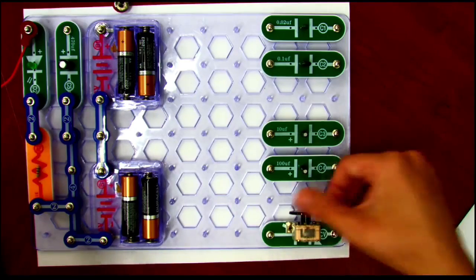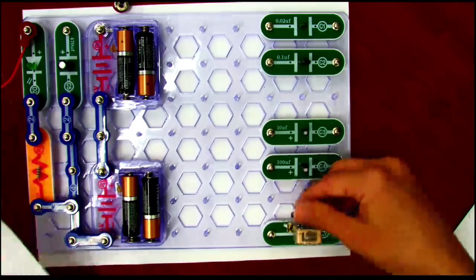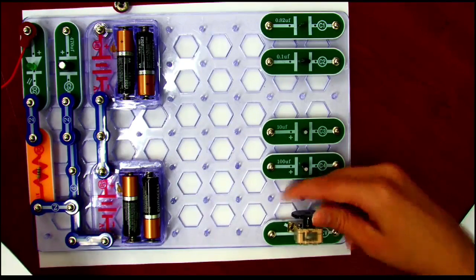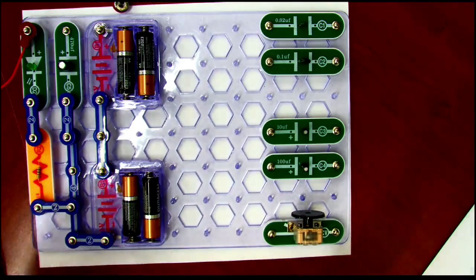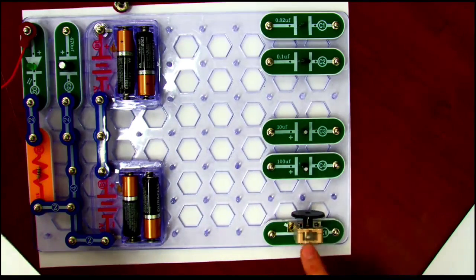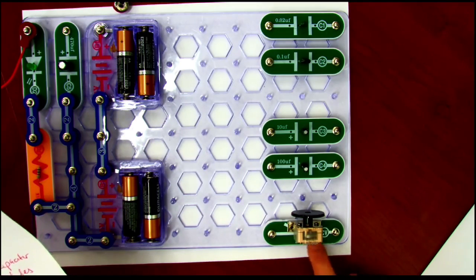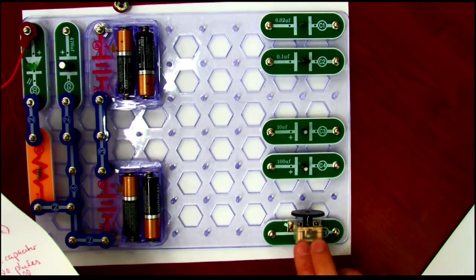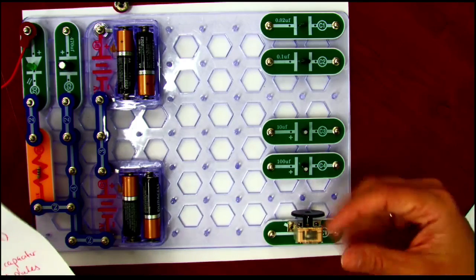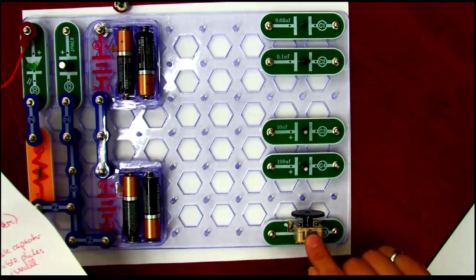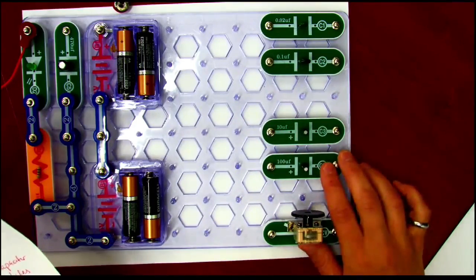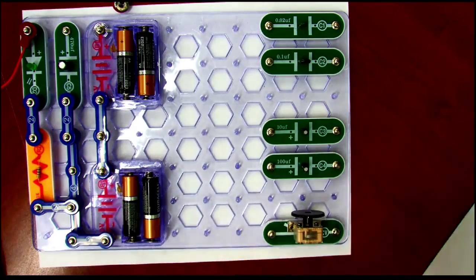And then this guy's a variable capacitor that you can turn the little knob on. You can kind of see into that window. I'll pass it around for those of you in class. It moves some plates in there, changing how much they're overlapping, to have those 2 plates standing off from each other. And this is for very, very small capacitances. It goes to 4 times 10 to the minus 5 microfarads, or to 2 times 10 to the minus 3 microfarads. So very small numbers of capacitance, but you can vary it, and this is used for high-frequency radio work. So when I pass this around, you can see some of these different capacitors. You might have seen them in different devices you've broken or taken apart or tried to fix.